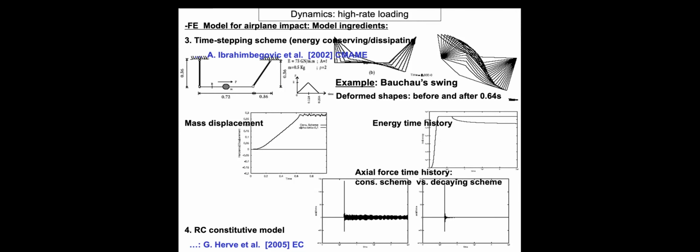So basically at that point, you have some kind of impulse that is trying to stretch this link. Before that, the swinging was done by the bending. So this is your beam bending. We'll talk about these beam models and stuff like that. And now you kick in axial deformation, which is typically much stiffer than the bending for the beam. And so this stirs up a non-smooth displacement. You can see that at that point you start having something like a non-smooth displacement evolution.